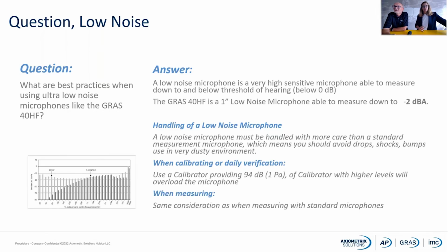When measuring, you should use the same considerations as when you are measuring with a standard microphone. And also some of the considerations we talked about before with low frequency components in your measurements. So in general, with a low noise microphone, be a little bit more careful, else use it as a standard measurement microphone.